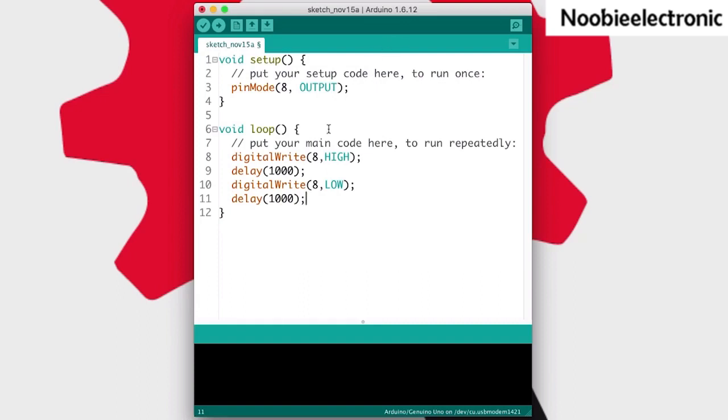So our LED on pin 8 will be turned on because we are writing a HIGH to digital pin 8. We're going to keep it high for 1 second. And then in line 10, we're going to write a LOW and keep that for another second. Then the loop finishes, so it means that it's going to go back to the beginning and execute the same instructions again. So that's it with the construction of the sketch.